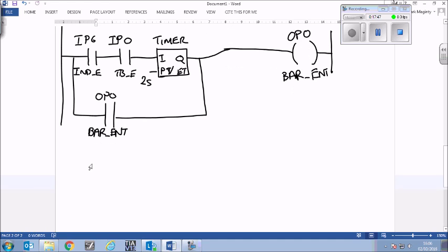So we know up here we need some type of stop mechanism, because currently right now, if we downloaded this, the barrier would go up and would never go down. Agree with that? Right, no way I turn it off. So we actually need to put in a normally closed in here. And we're going to control it by a different network. Okay, and we're going to use a thing called the memory bit. We've used these before as well, M0.0.